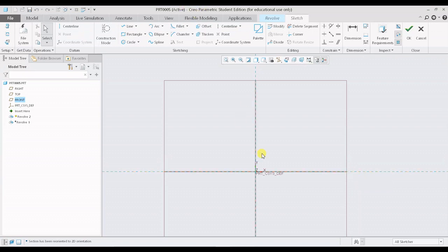So right now I want a cylinder to be standing on the ground. So I will be selecting the vertical axis, and I will be creating the geometry on the right hand side of the vertical axis. So rectangle is selected and a closed loop is created. So you have to ensure over here that whatever sketch you are plotting or whatever sketch you are sketching on the layout, it has to be a closed loop. So right now I'm not following any dimensions, just pardon me.